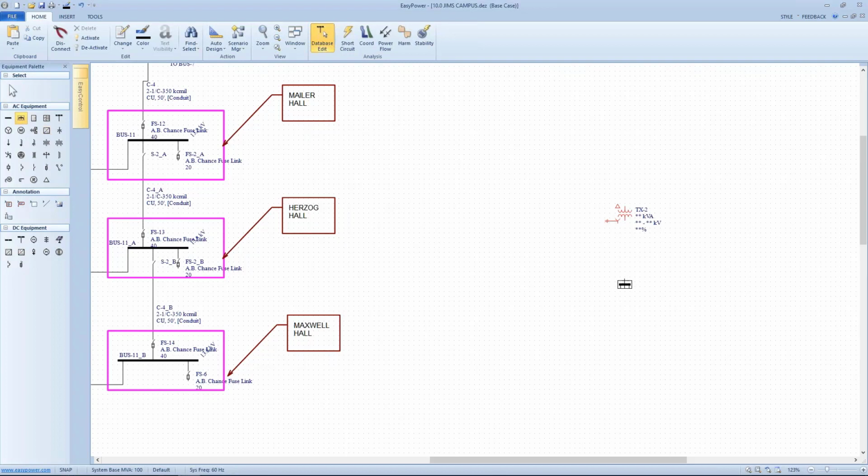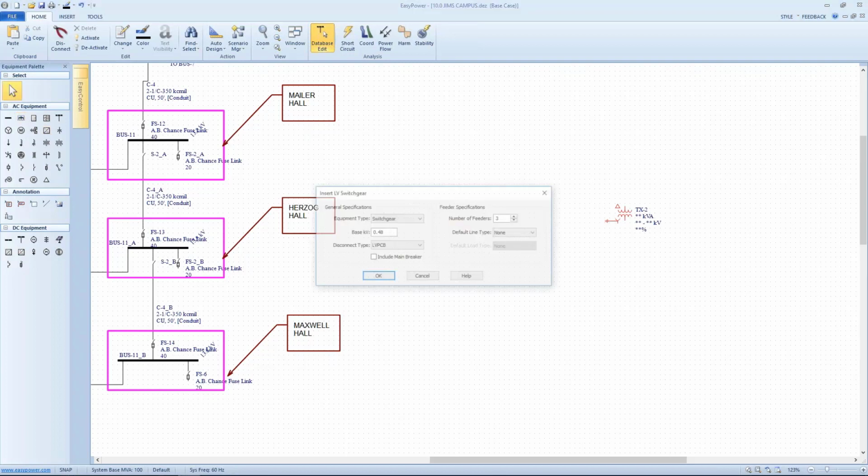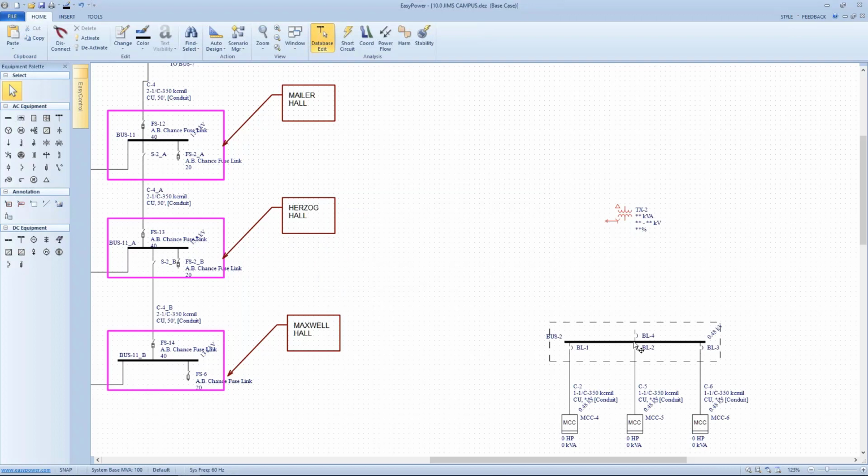this building thusly. So I'm going to use a switchgear wizard. Start off with 480 volts. We have low voltage power circuit breakers in this particular building. We're going to include the main circuit breaker, have 3 downstream feeders. Everything's going to be connected with cables. And in this case, we're using motor control centers. So as we build this icon here,